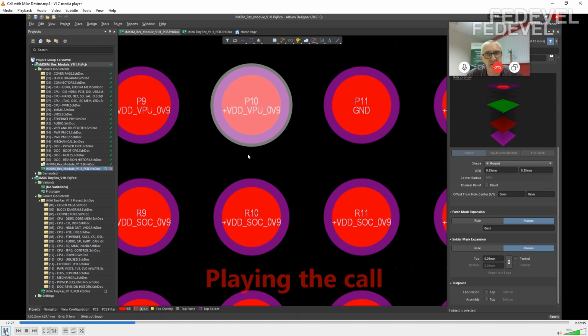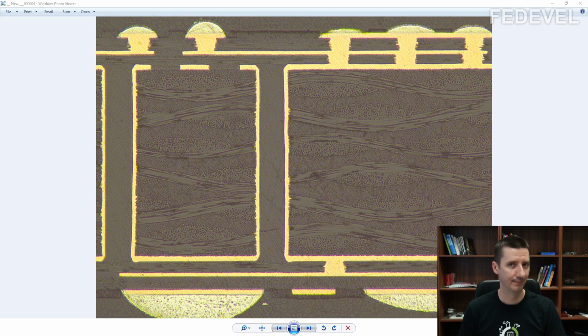It's just a time constraint, because we have to grow the copper back into the barrel of the hole at a low current density to avoid trapping any solution or air in the middle of the hole. Okay. Because what will happen is obviously the hole will close quicker at the knee of the hole.